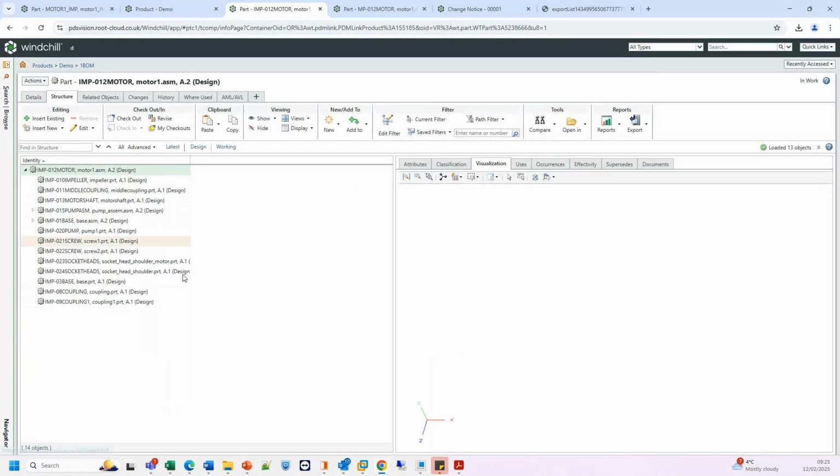Yeah, took a second, but there we go. And as you can see, we have our EBOM within that structure now. All of the relationships and links to those parts, all through that Excel spreadsheet. This can save a lot of time for anyone doing their configuration management, as downstream applications and systems have the ability to export information into an Excel or a CSV, and then this can easily be manipulated into the correct format for Windchill to absorb and create that structure and those parts.